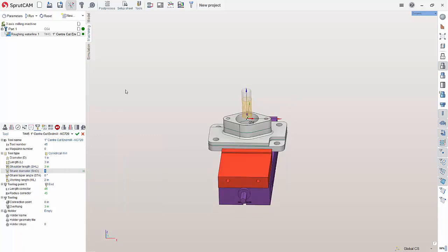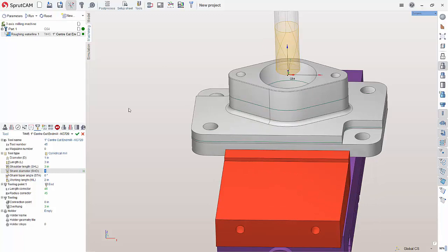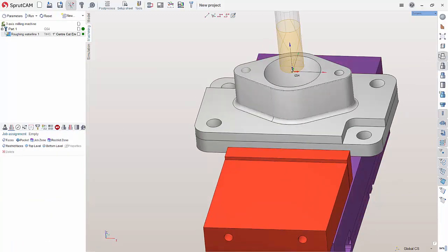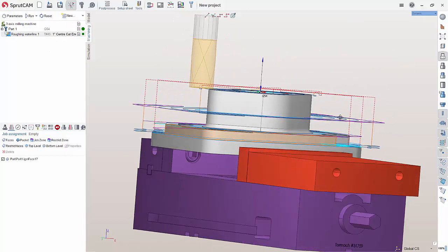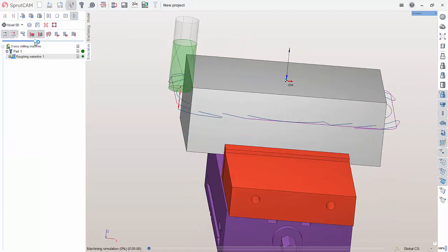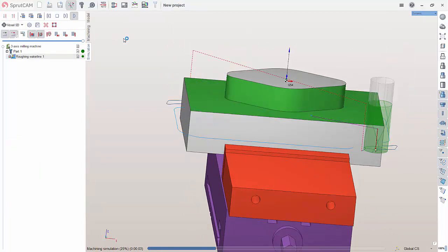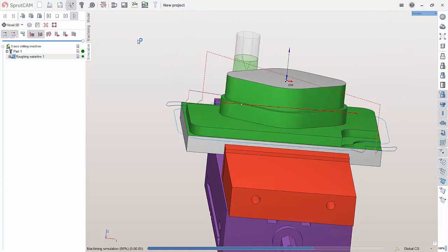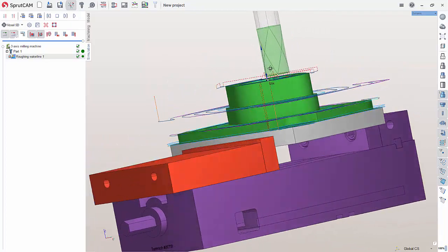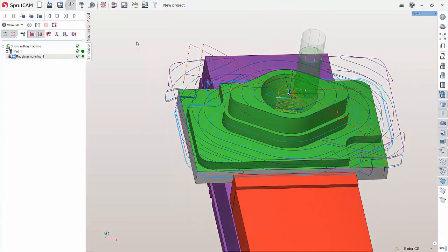All right, so we just got a tool here, and I'll just go back to job assignment, and I want to turn on my geometry view here, choose that, and say bottom level, and that's just so it doesn't go below that. All right, and I'm not going to completely machine this part out, but I'll just, just to show you. And there you go. So if you were done with this part, you're done. You can go ahead, go into post process and let it go.